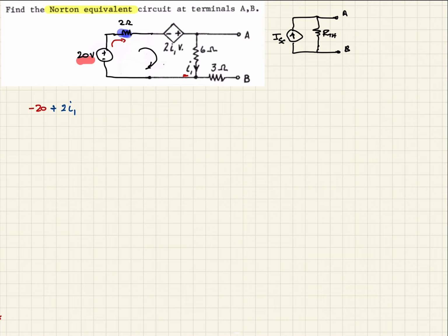And then we come across a voltage source, which is defined. It's a current-controlled dependent voltage source. And so we see we hit the negative sign first. So let's identify this. So this is our voltage source. And so the voltage is going to be minus 2I1. And then finally, as we come down through this resistor here, we'll define that with this color.